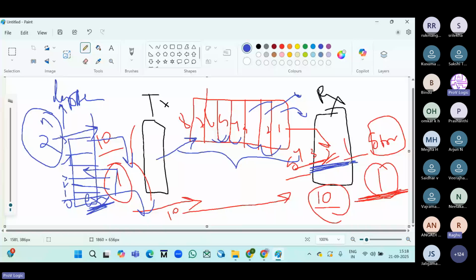Yes, there are a lot of versions, like AXI 3. Versions mean mostly the features will differ. The APB protocol is a very basic protocol where we have few signals: clock, reset, address, data, write or read, PREADY, PSLVERR, PPROT, less than 10 signals.